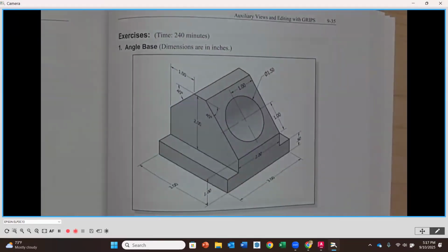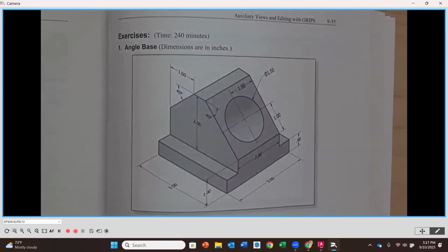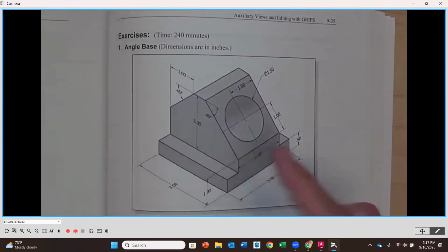And again, we're not going to be dimensioning here, but anticipating that, like I said earlier, one of the rules of dimensioning is I can only dimension to a feature that is shown with object lines, where I can see the edges, and that it's the true size and shape. So where I see a hole, I have to dimension in the view where it is a round circle. To do that, I'm going to have to look at a different angle other than my principal views.